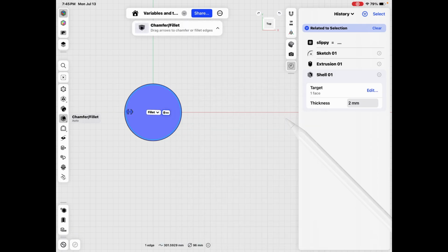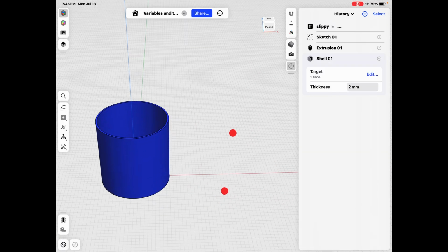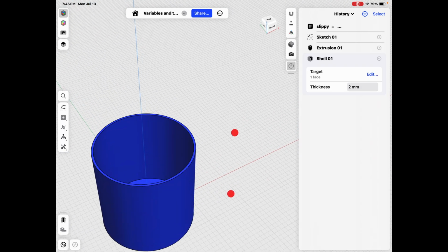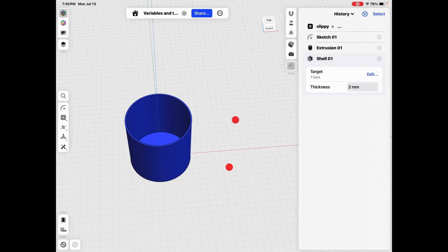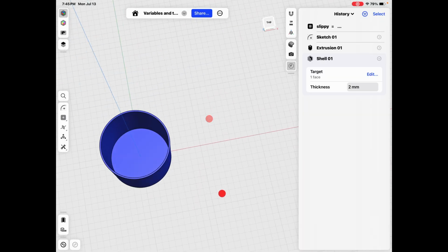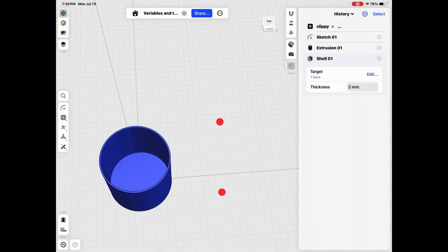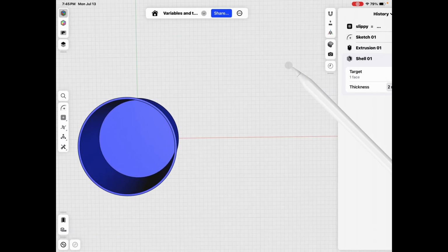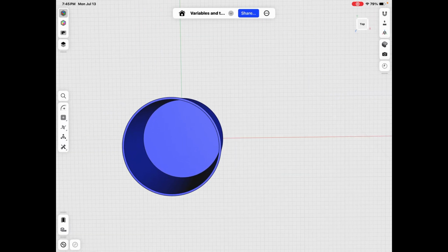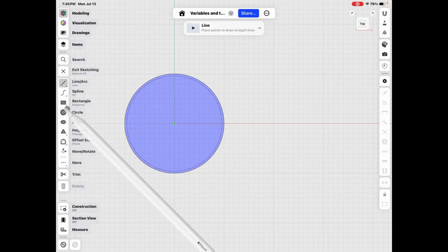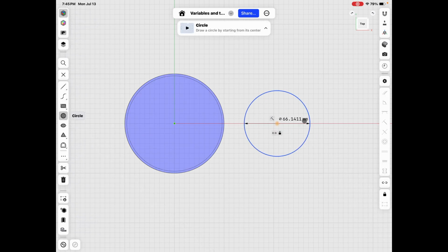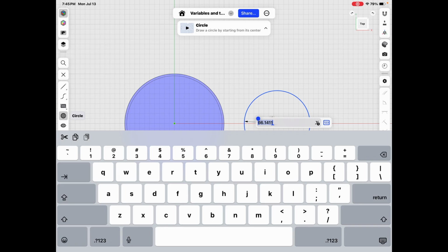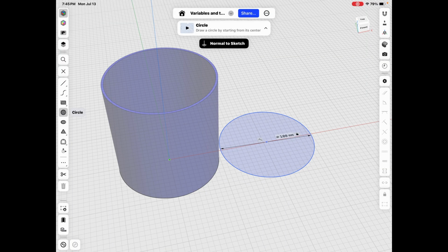All right, now we need a lid. And the lid needs to have the tolerance added to it to be able to fit, or removed from it in order to fit. Because if we did it 0 line and 0 line, it would not fit because there's some squishy outiness. And so what we want to do now is let's do another 100 millimeter for the lid. 100. All right. Let's extrude that up a little bit.